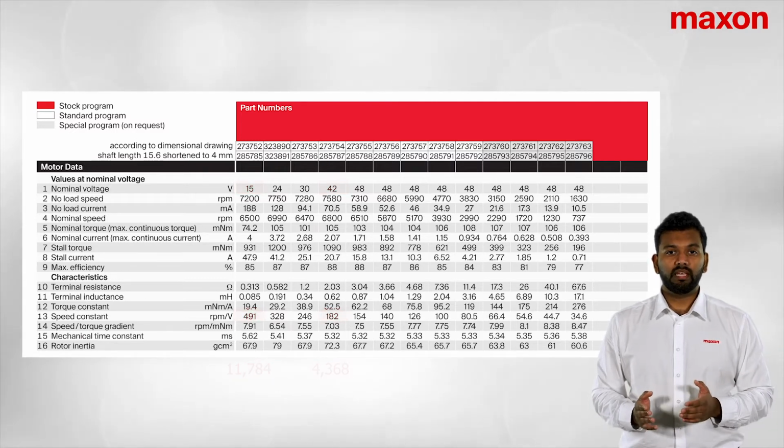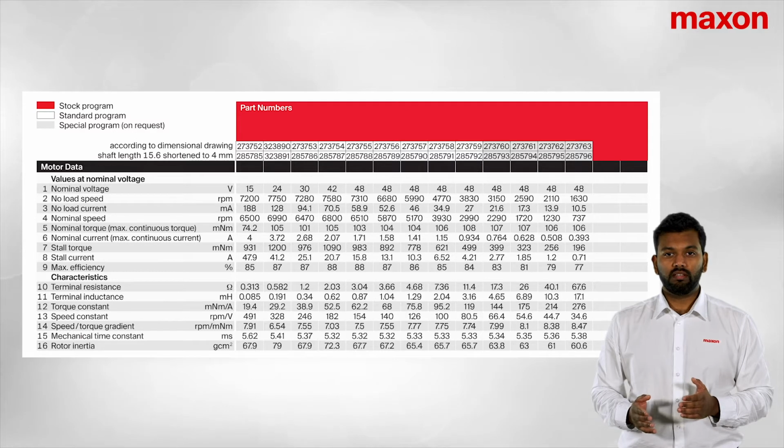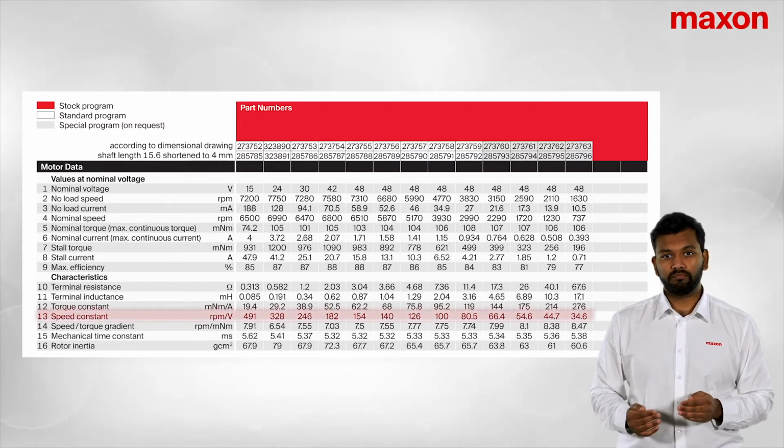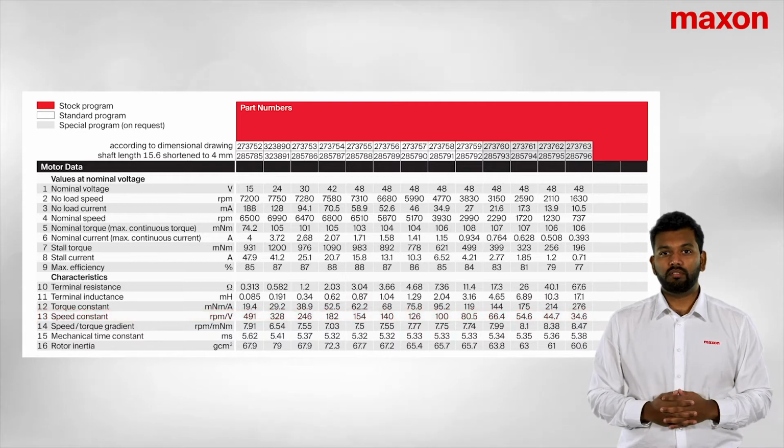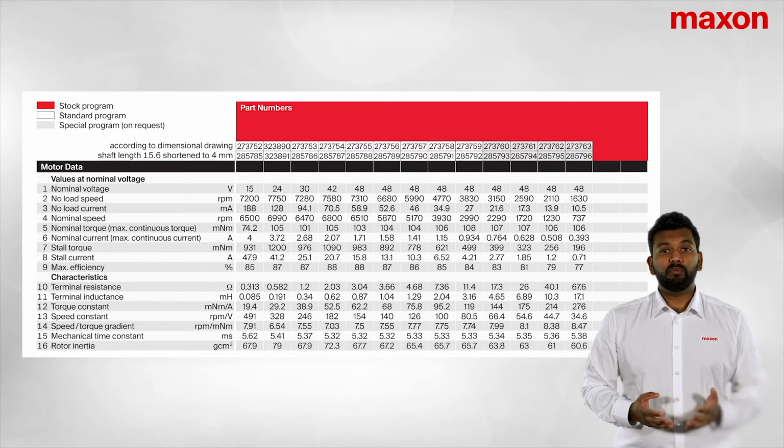So you can see from here, when you come to select the correct motor for your application, you need to choose the correct winding. And this primarily focuses on the speed constant. So there you go. This is a point that you must always look at when selecting your winding. Now let's move on to current.